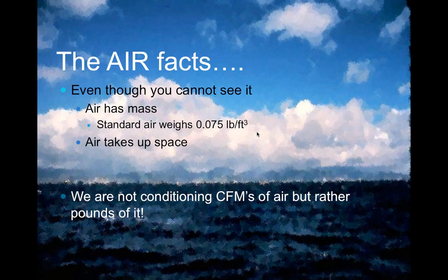Something really to think about and to consider is that air, even though you can't see it, has a mass. Standard air at standard air conditions does have a weight of 0.075 pounds per cubic foot. It does take up space, although it can be compressed. It has a specific density. So it does require energy to move this mass of air.